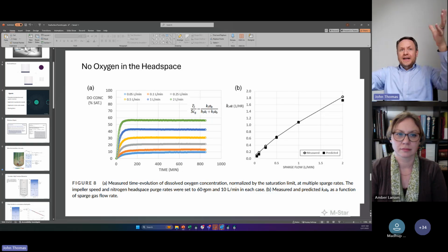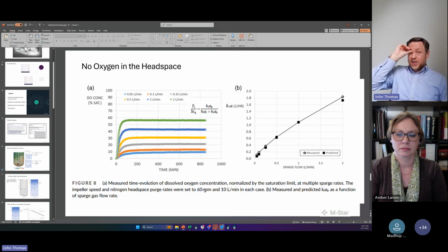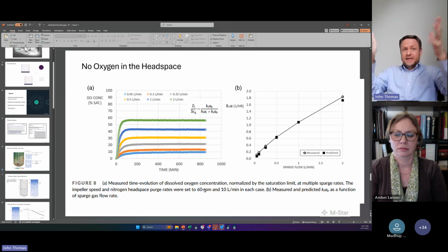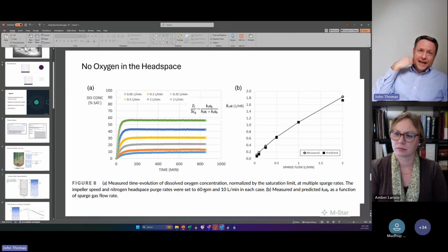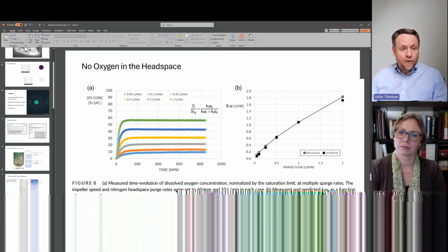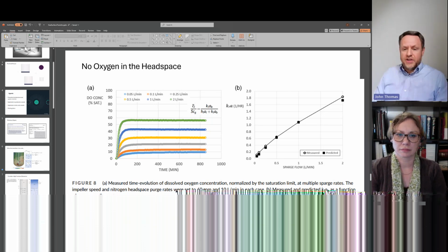It is getting an interface down, in this case down a shaft and outside the impeller blades to be cut up. Yeah, we can do that. And by induction, we can certainly do a vortex coming down and being ripped apart to form individual Lagrangian bubbles. We do have Eulerian-Lagrangian coupling that allows us to look at how, once a free surface breaks up and forms into bubbles, those bubbles then further break up or buzz around the system as Lagrangian point objects.